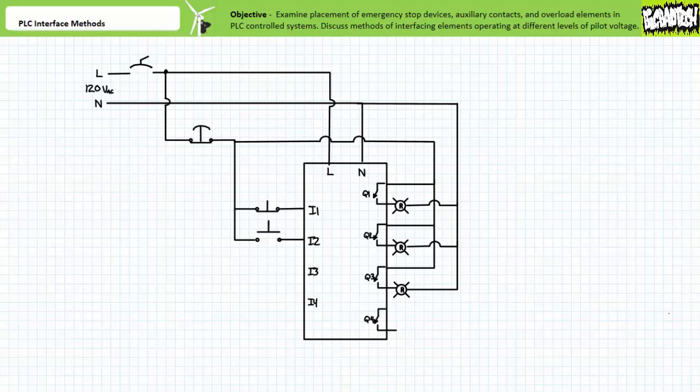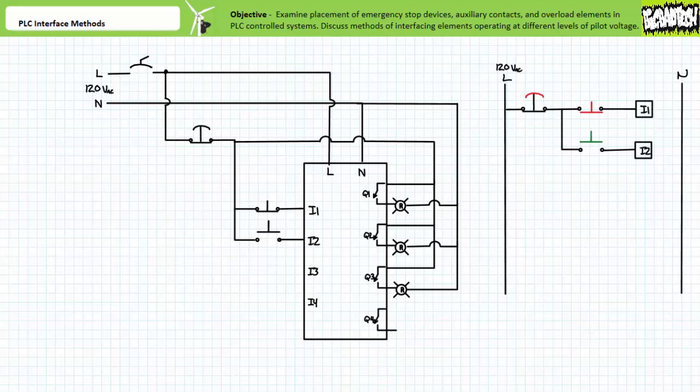Consider our present configuration illustrated far more efficiently in the following fashion. Here, the hardwired connection between the e-stop and the two downstream field input devices, the normally closed momentary contact red push button and the normally open momentary contact green push button, is made pretty explicit. However, the field signals kind of disappear down the rabbit hole of the appropriate PLC inputs. This is to imply that an isolation between the field inputs and the PLC exists, and the PLC program assumes responsibility for all incoming transmissions from this point on.